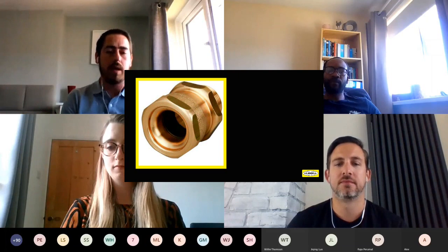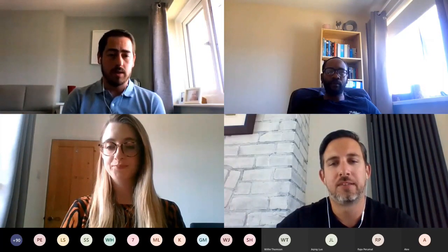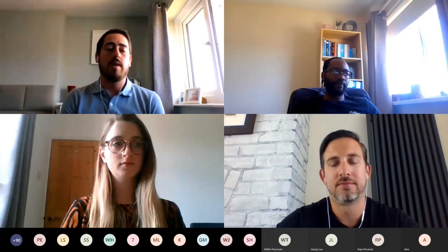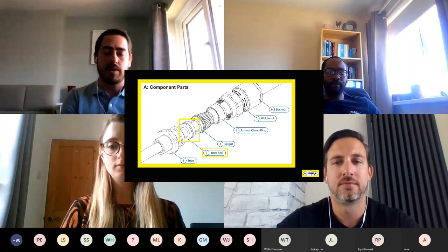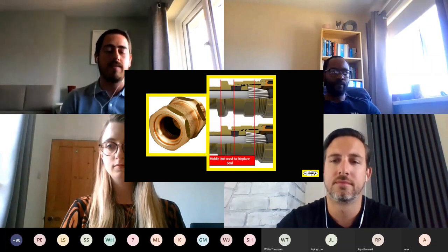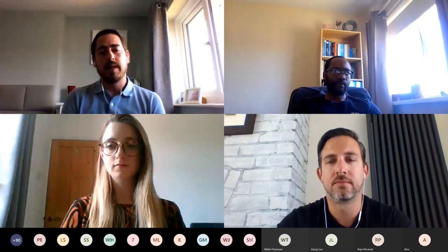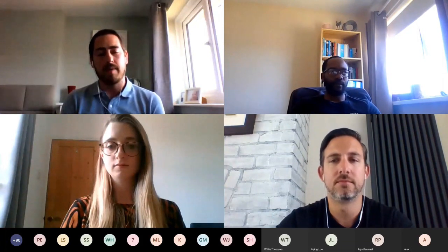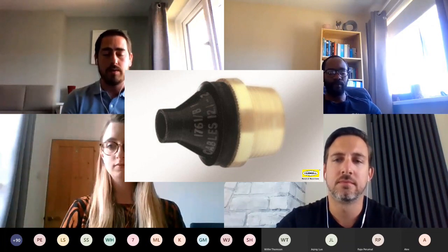On our unarmoured cable gland range, so our 501421 or our 501423, these are also used as an internal compression seal to give you your EXD requirement. If you go inside of the cable gland and look on the inner sheath, as I said, this compression seal can be used there too. Obviously, this is a mechanical type seal. This is an active seal, something where you have to apply some pressure to it for it to do its job. We also have the diaphragm seal, which is used in our 501453 universal range.